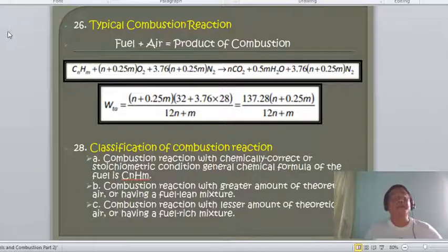Just put the hydrocarbon fuel plus oxygen plus nitrogen, since the nitrogen is 3.76 times the oxygen in the composition of air, yielding CO2 and H2O. Then designate variables to oxygen, CO2 and H2O, and balance the carbon and hydrogen at the left side and at the right side, and you will obtain the same balanced equation.